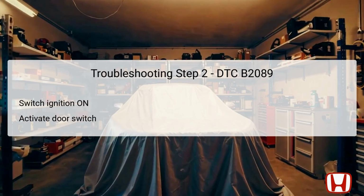In this step, after clearing the DTCs, turn the ignition switch to the on position or press the engine start-stop button to activate the electronic systems. Subsequently, it is essential to turn the power sliding door main switch on. This step prepares the system for testing the operation of the right power sliding door switch.